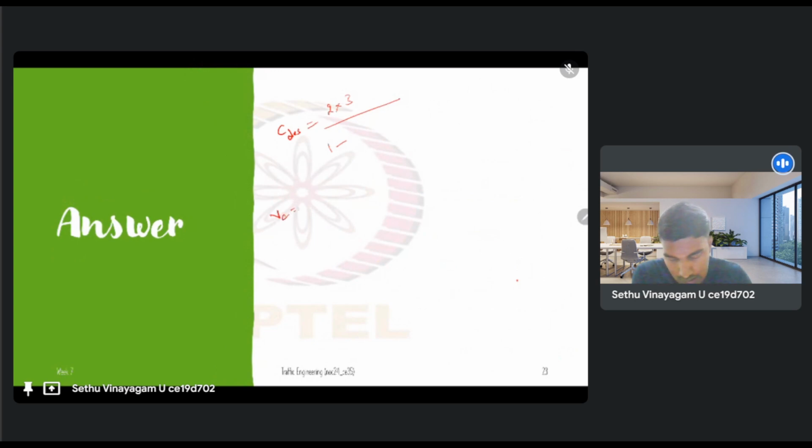So VC earlier was 600 plus 650, but now it is 400 plus 650, which is 1050. Okay, so because we have an additional lane, the critical lane volume for the eastbound movement has reduced. Okay, so this part has changed. So therefore VC has changed. So 1 minus VC.